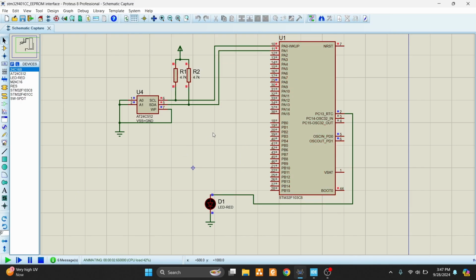We'll need to monitor the EEPROM pins. That's all we need to do. Now let's wait for the transaction on the I2C pins, I2C and EEPROM. The EEPROM is connected through the I2C protocol. We are using the GPIO pins, manually toggling the GPIO pins to generate our I2C.